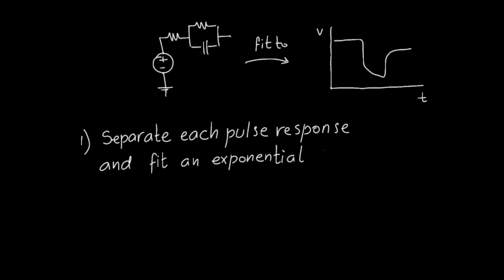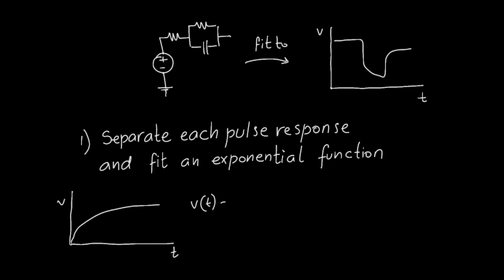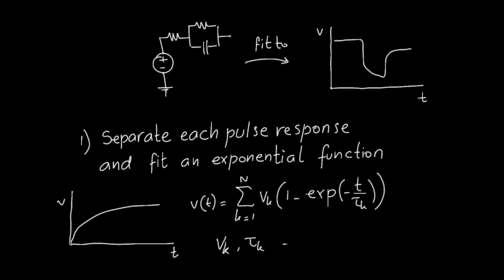It looks something like this if the relaxation starts from a fully polarized state, and it gets a little more complicated for partial initial polarization. For example, when the current pulse is short compared to the battery characteristic time constant. Automating this process so that it is applicable to any experiment requires some MATLAB coding to identify the beginning and end of each pulse and process them individually.